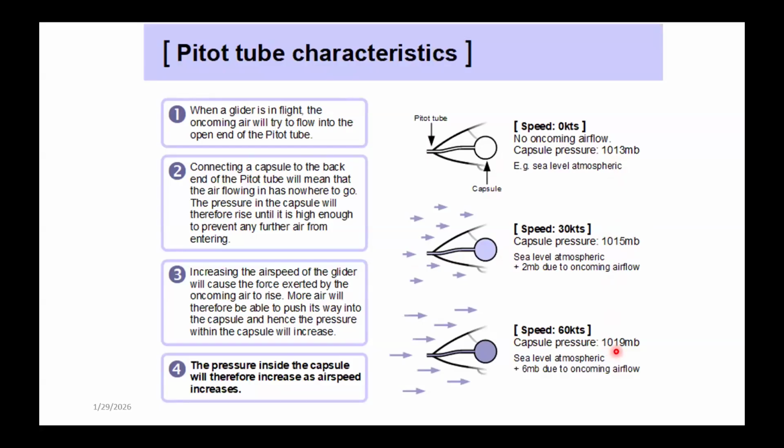Some of the Schempp-Hirth models have problems with the way, when they went back and added the nose hook to the Ventus or Discus at some point, then while you're connected to your tow plane, if you use a wiffle ball on the end of the rope, that can interfere with the airspeed reading while you're on tow. Okay. We'll talk about the digital version of this. We're talking about the analog version right now. We'll talk about the digital version down on about 5 slides.